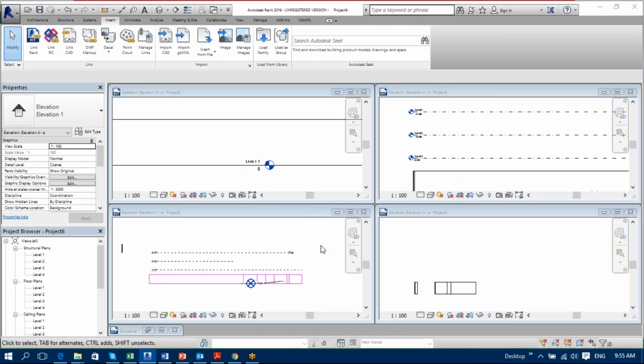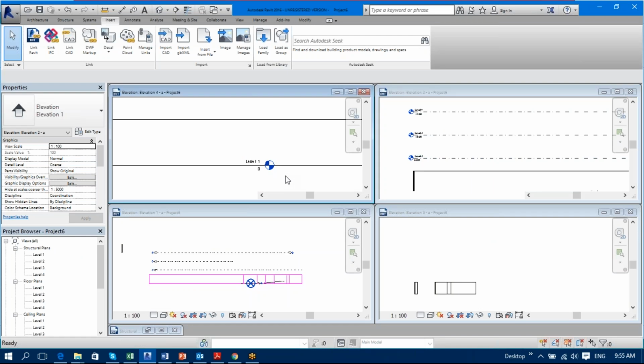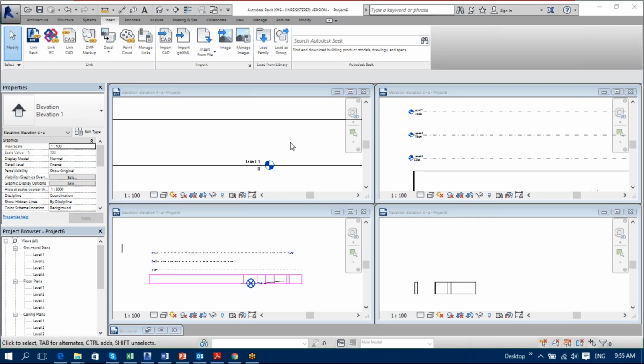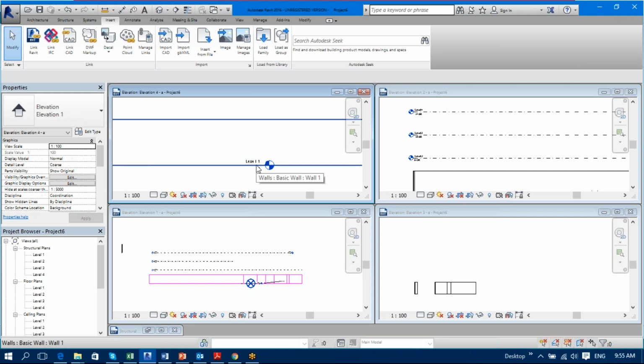So, as I'm saying about the levels, if I go down over here, in order for me to select these levels, I press tab. Now the status bar is showing. If I select now, I would end up selecting a chain of walls or lines. Again I press tab. Now it's saying walls. Again press tab, tab, tab. See, levels came. This is a shape handle, wall 1. Are you all able to see the status bar? Tab, tab, tab. Now it came, level 1.